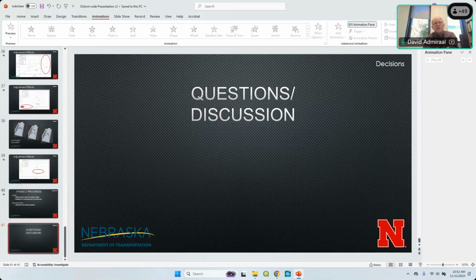So as I showed you, we're raising that tailwater tank, and a big part of our problems was that really high slope limited us to really high Froude numbers. In fact, if we had installed that gate and it had worked properly, and we had made adjustments to make it work properly, we would have just gotten higher Froude numbers. That's all we would have gotten by lowering the drop, by reducing it.